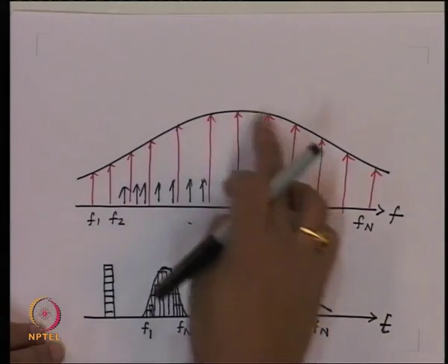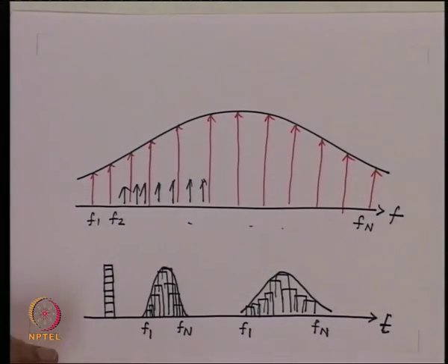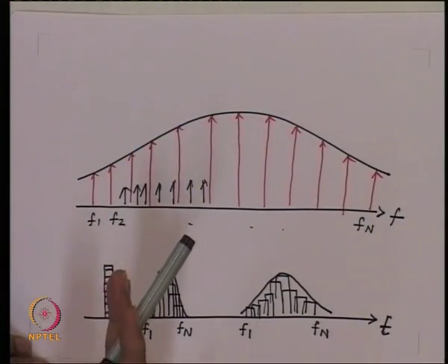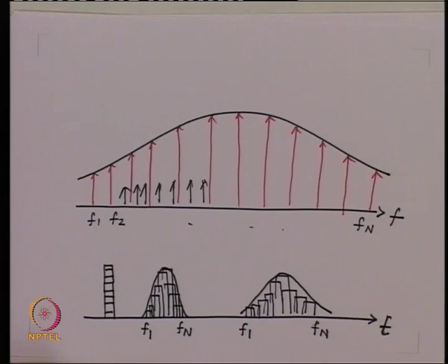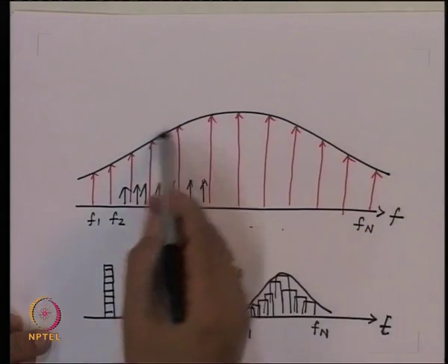More or less it is decided by the spectral width of the source. You can ask, what is the shape of the pulse as it travels on the optical fiber? Initially the shape would resemble the intrinsic shape of the pulse which you are transmitting. But as you proceed further, you will see that this shape slowly will be dominated by this profile.